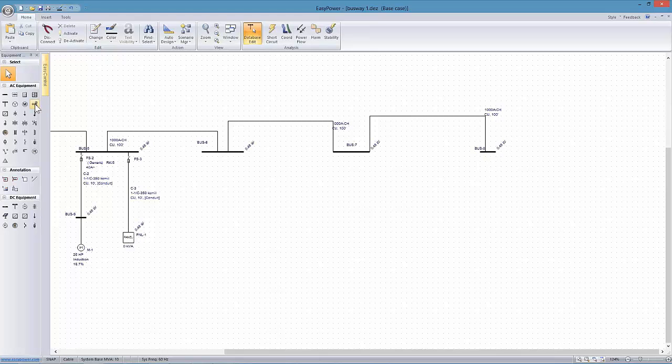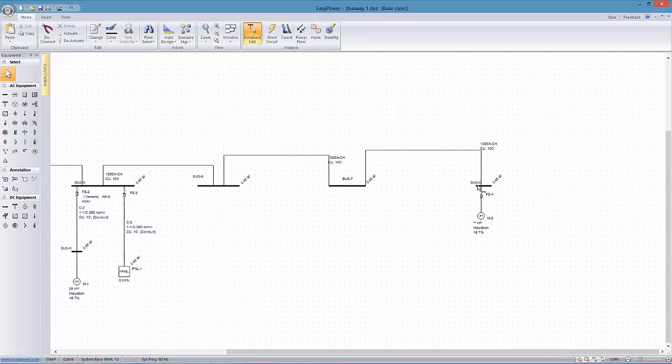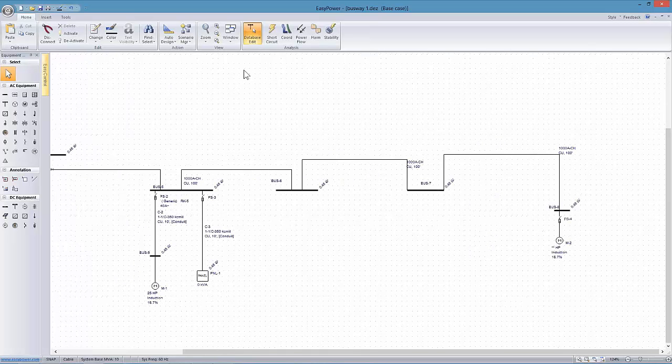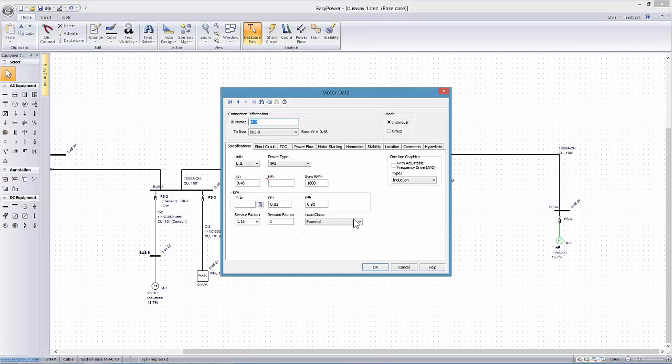So as we get down to the end of that 600 feet, we will end up with some potentially hairy arc flash incident energies, even that could be carried down to the drop point if we haven't got the proper protection.